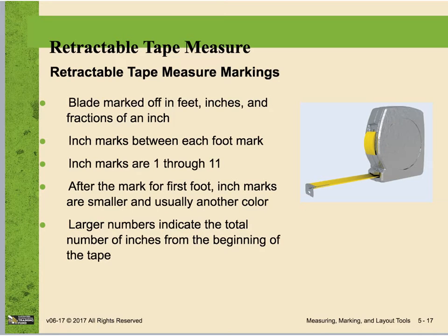Retractable tape measures start out anywhere between 3 feet to a couple hundred feet in length. They're used to measure distances between objects or heights of objects. Make sure you use these tools correctly. Do not allow the tape measure to slide in all the way without slowing it down. Never put your finger on the side of the blade or it will cause you to get cut. Never bend the tape measure back and forth as if you're playing with it. This makes the blade weak and will cause it to break.